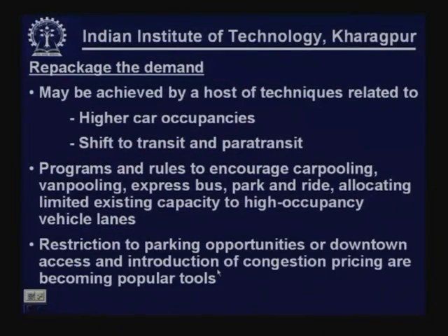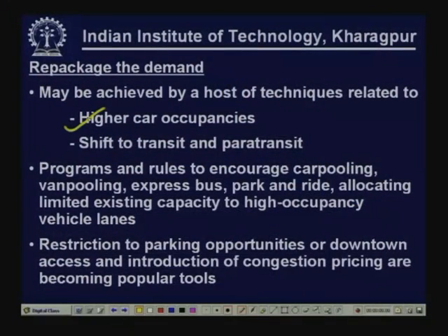Repackage the demand. Remember that we are talking about repackaging, that means total demand may still be the same in terms of person movement, but we are trying to repackage the demand. Let us see how we can repackage the demand: through higher car occupancies, shift to transit and paratransit. So, what will happen? The same volume of passengers may be transported, but with a lesser number of vehicles.